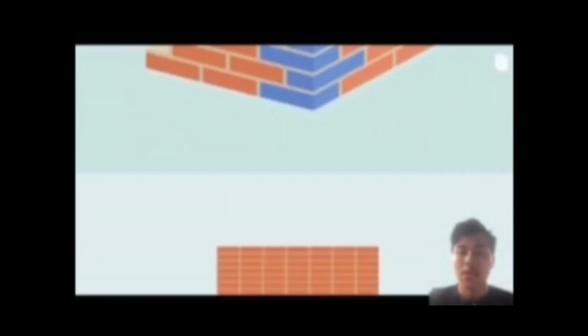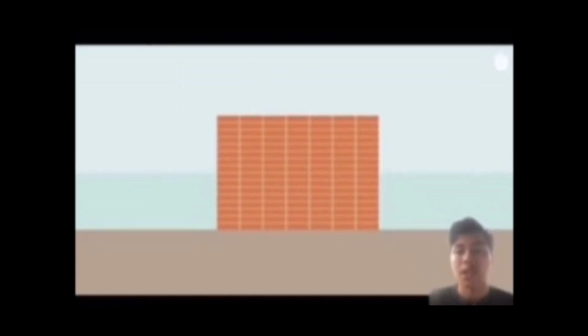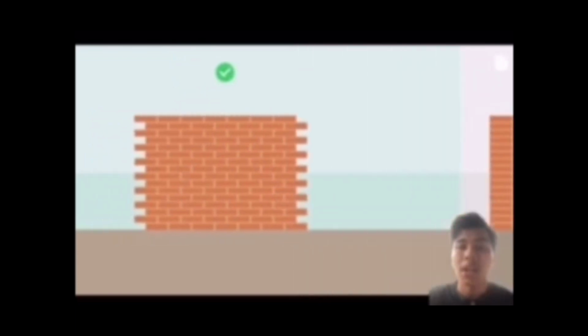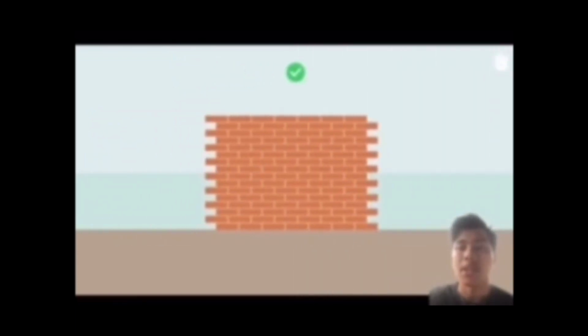Spirit level is an easy measuring device. We just have to trace the bubble movement. For example, in our figure, the label covers 2 digits of the scale on one side. That means the actual inclination is 0.02 per unit. The base of the spirit level is called the reference plane. It sits on the machine part of which straightness or flatness is to be determined.